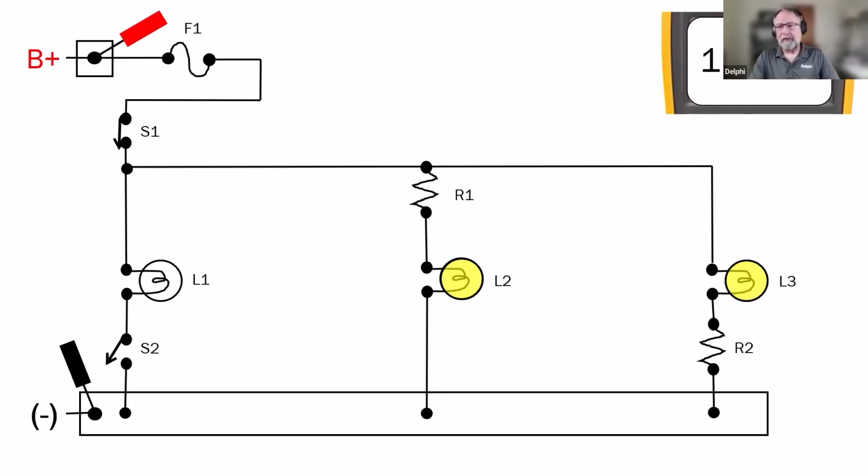So now, in practice, how is it that we're going to figure out that these are underperforming loads? Both these lamps are dim. Just looking at them, there's no way to tell whether it's a power side high resistance or ground side high resistance. We're going to have to bust out the meter and see what happens here, okay? We're going to start by measuring voltage at the source. So you guys can see that in this particular case it's being fed 11.96 volts at the B plus terminal and the negative terminal down below on chassis ground, we'll call it.